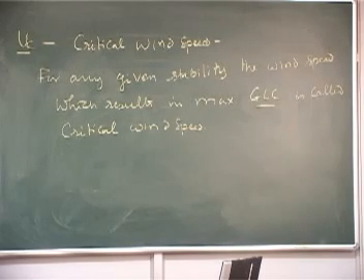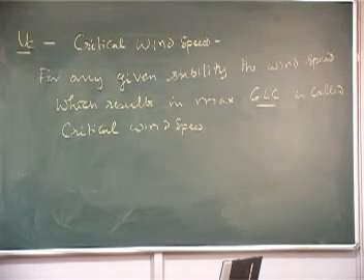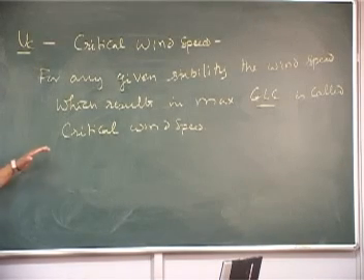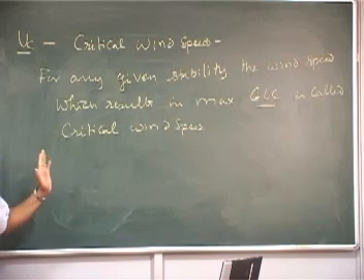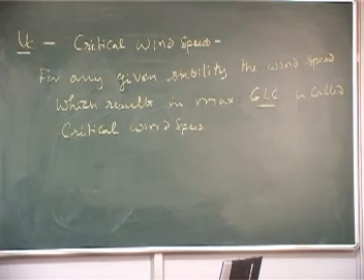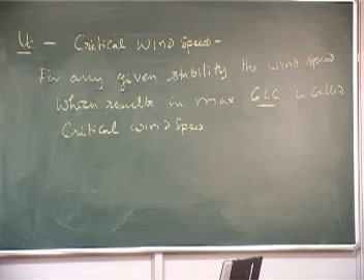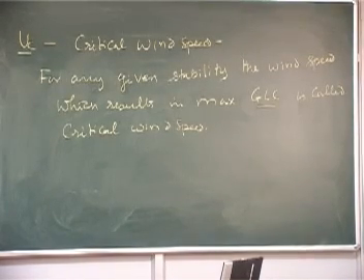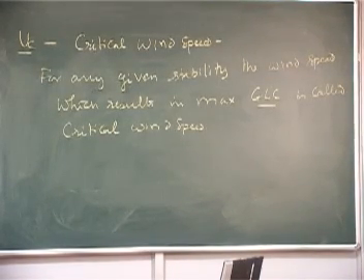So what do we do? We are all the time interested in where the maximum concentration will occur. Okay. But what I don't know is that critical wind speed. Okay. Although there are many formulations that have been developed where you can find out mathematically where the concentration will be, what you need to do is differentiate this one again with respect to wind speed, right, okay, and find out this thing and put the formulation for the maximum concentration and things like that.